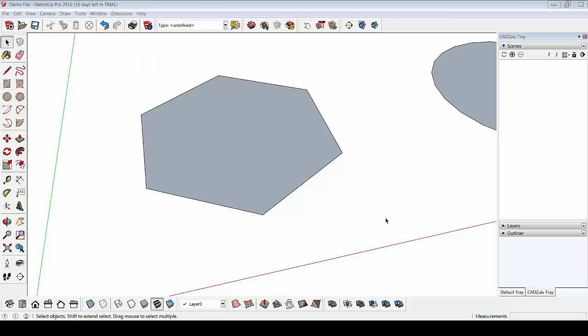Right, SketchUp's also done a lot of work in 2016 on the off-axis inferences. So improved parallel perpendicular inference display with the down arrow. As I hover on various places, you can see if I do hold down Shift or even the down arrow, it starts doing something like this. I can inference, I can then left click, and you can see it's locked. It does actually highlight the edges, and as I start drawing again, it does show me where it's locked in.